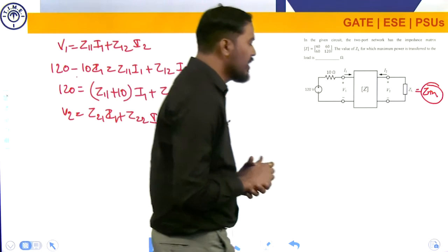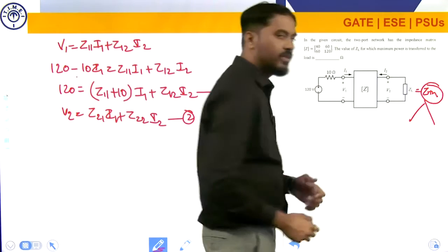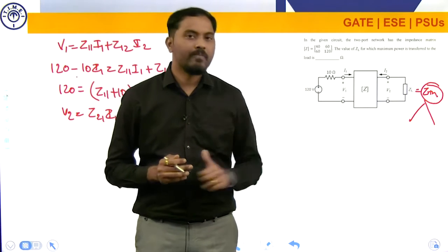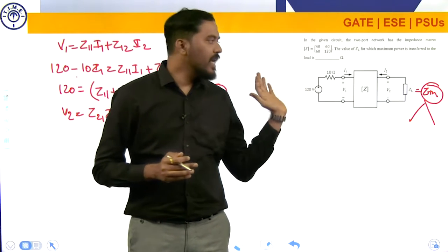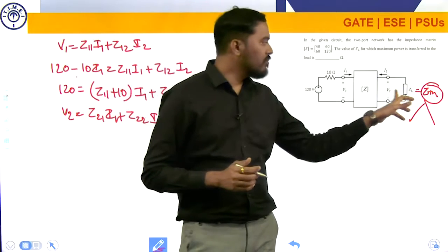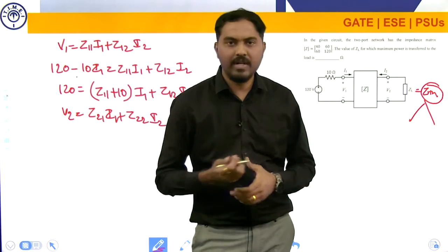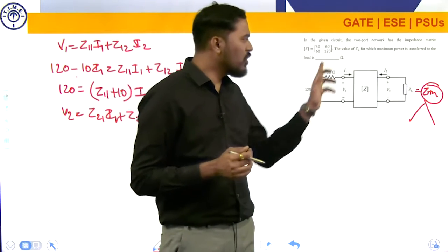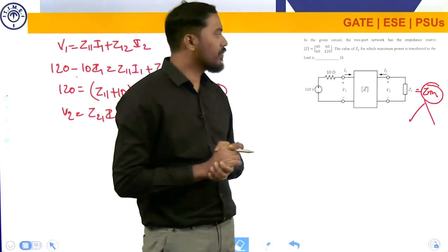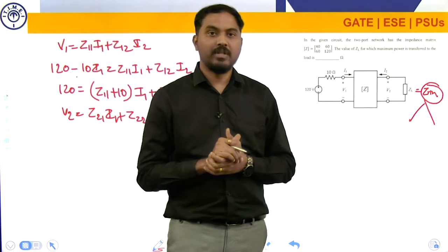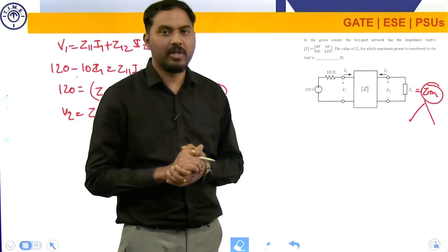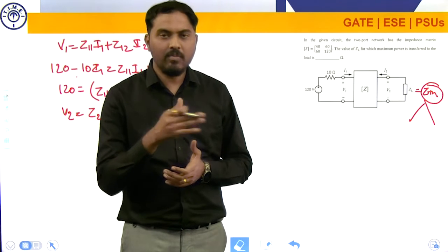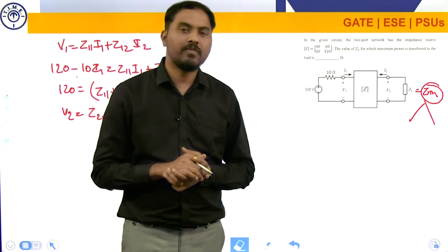How to calculate ZTH? Now, ZTH can be calculated in two styles. One is our traditional method, where you remove the load, open circuit the terminals, deactivate all energy sources and look from the open circuited terminals, and the equivalent resistance is your ZTH. You do that by network reduction technique, but do you know what is present inside this box? You have no clue. Here comes another method, a simple and interesting method, the test voltage or test current method. For example, if I give you a small resistor and I remove the color coding on it, how do you measure the value of this resistor?